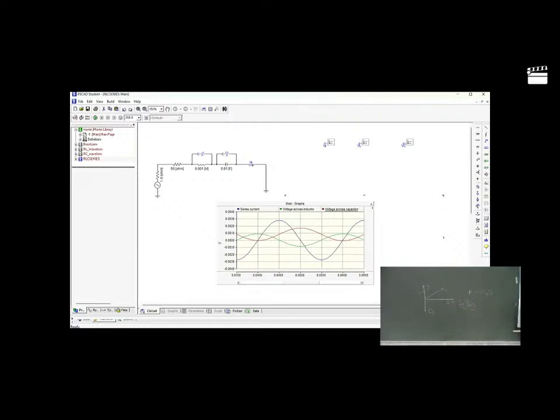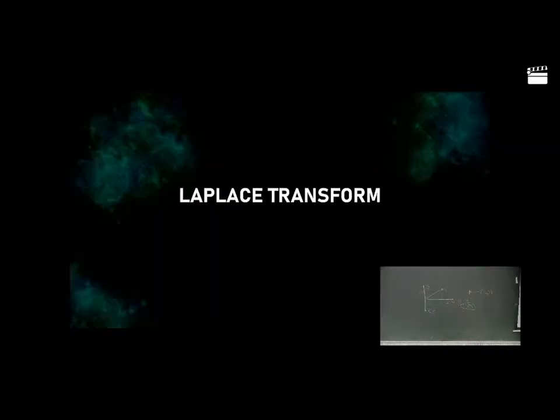So you go next to Laplace transform. Why do we use Laplace transform? Laplace transform is a very powerful tool which we use to solve certain differential equations. In electrical engineering, you often encounter differential equations like the RLC circuit or the normal series RL circuit. All those are made up of differential equations, and if the number of circuit elements is more, the order of the differential equation similarly increases. In order to solve this, we use the Laplace transform, which converts the differential equation into an algebraic equation, as we will see just now.